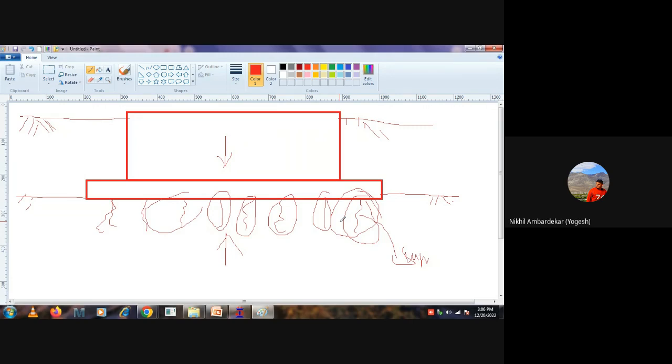Generally, it is given by the geotechnical engineer through its soil report. This subgrade modulus of reaction is given by the geotech engineer. If it is not, then maybe we need to assume something. How to calculate that?